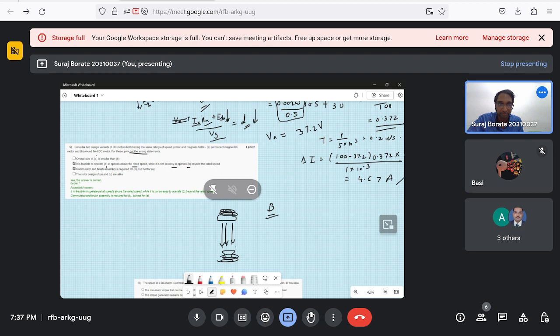In this case, the maximum torque that can be generated for a given speed can be arrived at from the consideration that power is constant. The torque generated remains constant at all speeds till the rated speed, or the torque generated increases as the speed increases from 0 to rated speed.